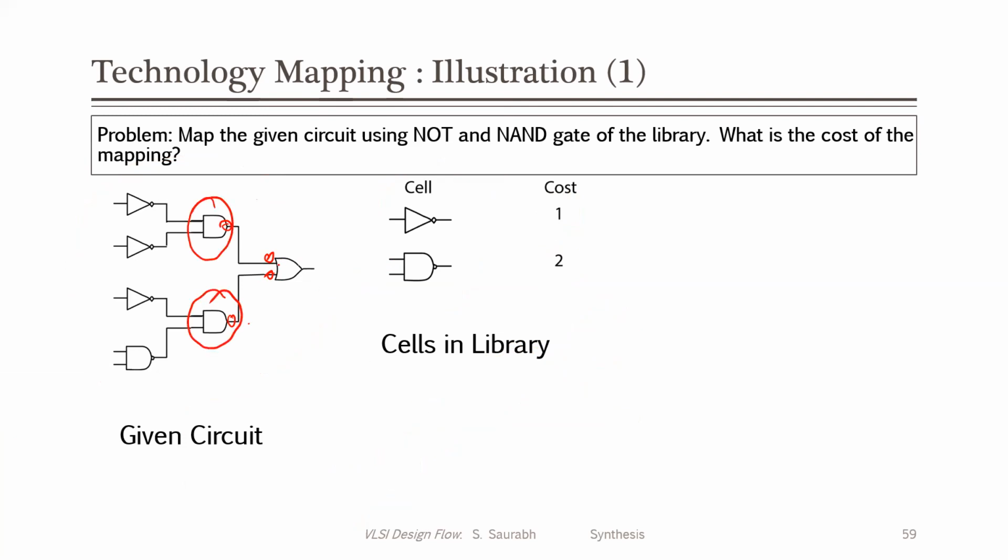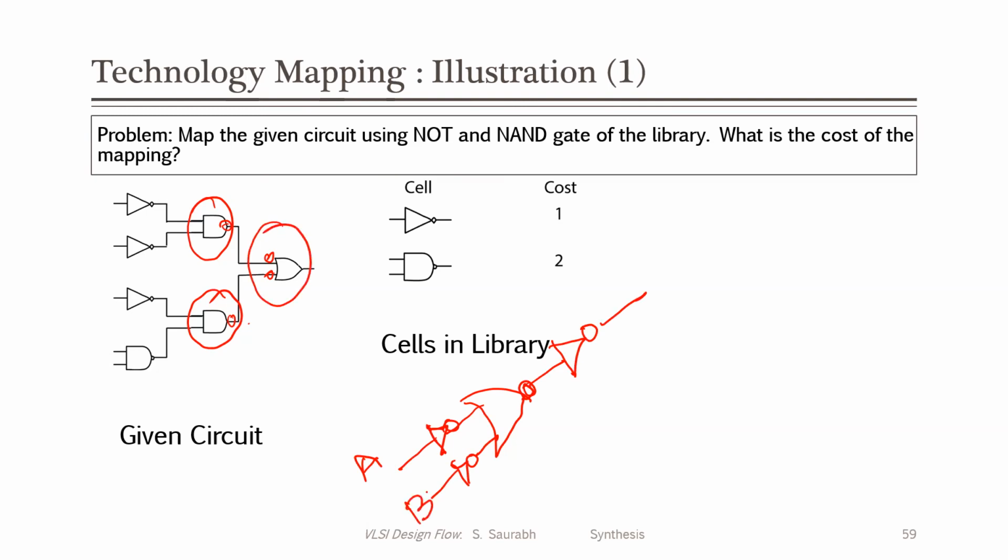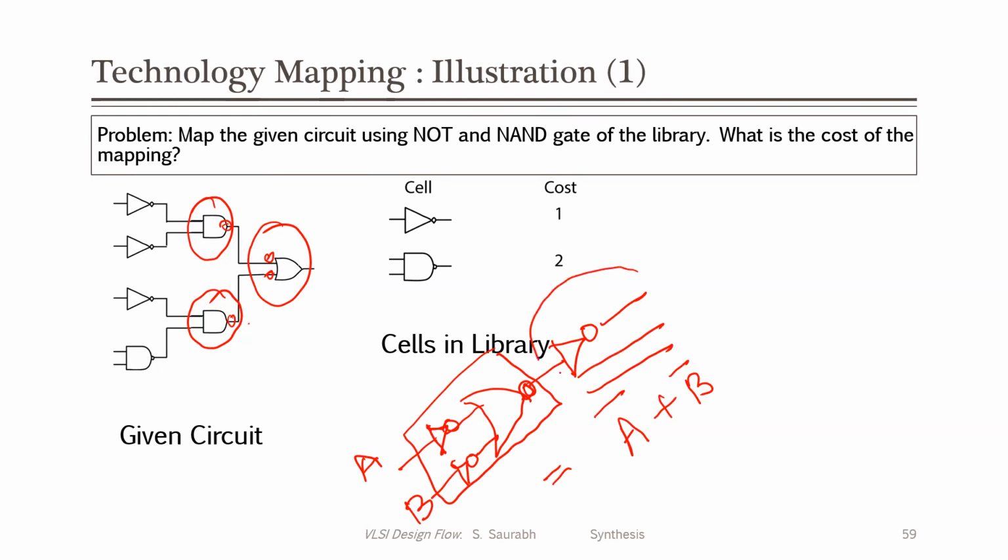Now, for this also we can use this OR gate, right? You have an inverter, and this is A, right? I can make this a NOR gate and put an inverter. It is equivalent to this, right? This is A, so it is the same as A bar plus B bar whole bar, right? This is this part, right? And then you take one more bar because of this inverter, right?